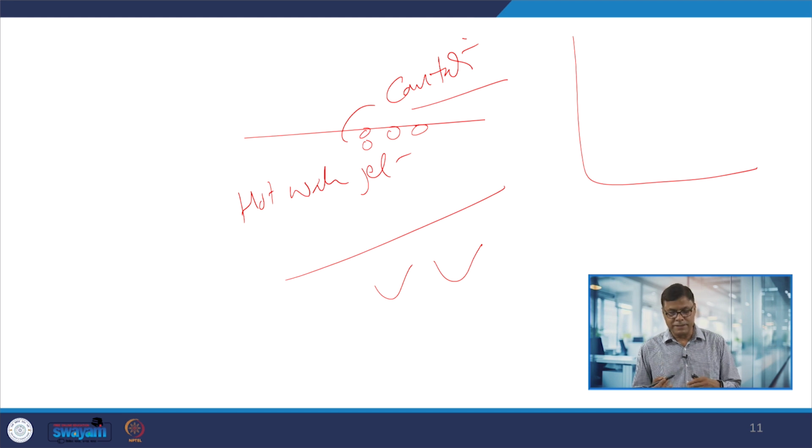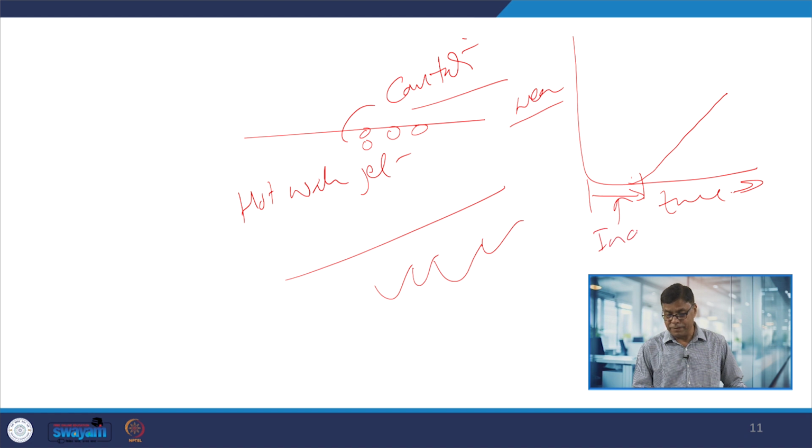Okay. Continuous pressure shock waves result in pits at the surface through the removal of the material. So, initially the surface may be smooth and there won't be any wear or erosion, but after some time, if we see the wear happening due to cavitation as a function of time, this is the time when the cavitation will be starting, known as the incubation period. Okay. And thereafter the wear will start, and then it will continue to increase.